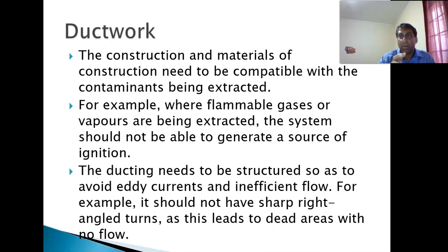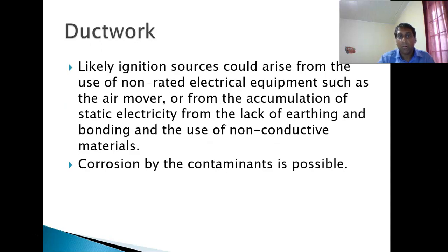Ductwork likely ignition sources could arise from the use of non-rated electrical equipment such as the air mover, or from the accumulation of static electricity from the lack of earthing and bonding and the use of non-conductive materials. Corrosion by the contaminant is possible, and again, that's simple.